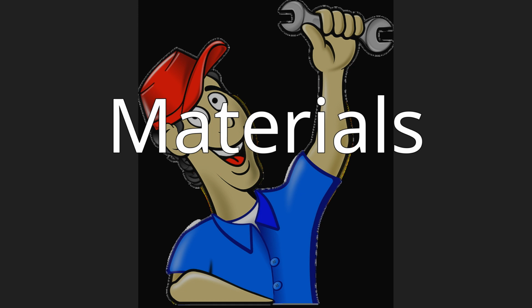Materials. The material with which a pipe is manufactured often forms the basis for choosing any pipe. Materials that are used for manufacturing pipes include carbon steel, ASTM A252 spec grade 1, grade 2, grade 3 steel pile pipe, plastic piping, e.g. HDPE pipe, PPR pipe, or LDPE pipe, low temperature service carbon steel, stainless steel, non-ferrous metals, e.g. copper-nickel, tantalum-lined, etc., non-metallic, e.g. tempered glass, Teflon-lined, PVC, etc.